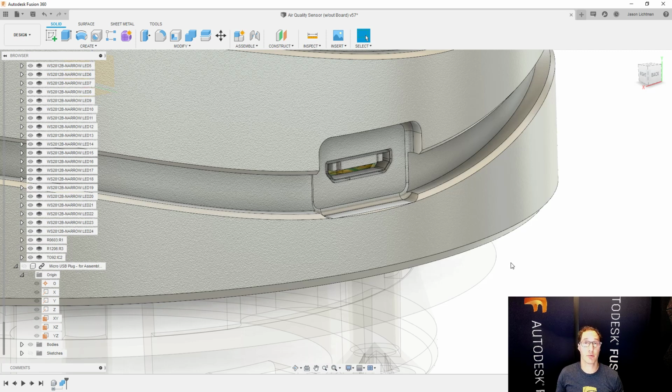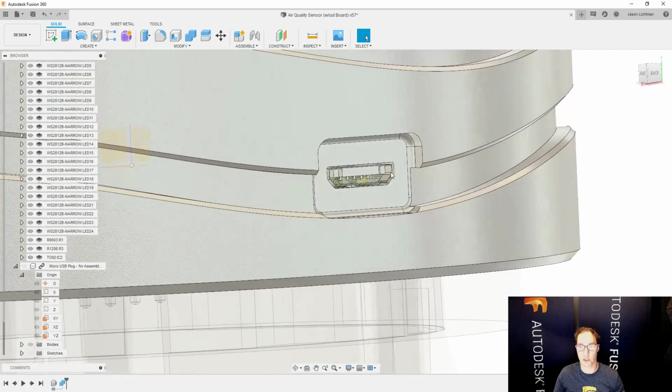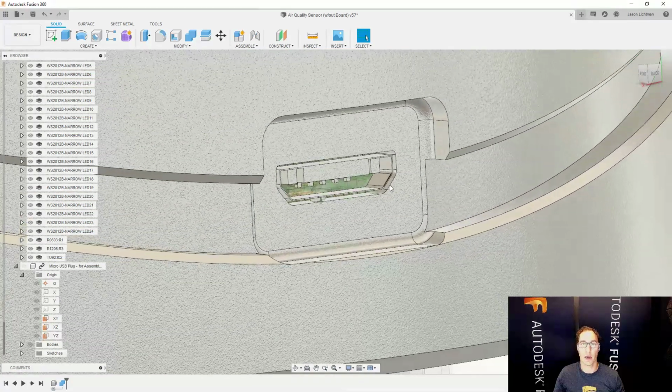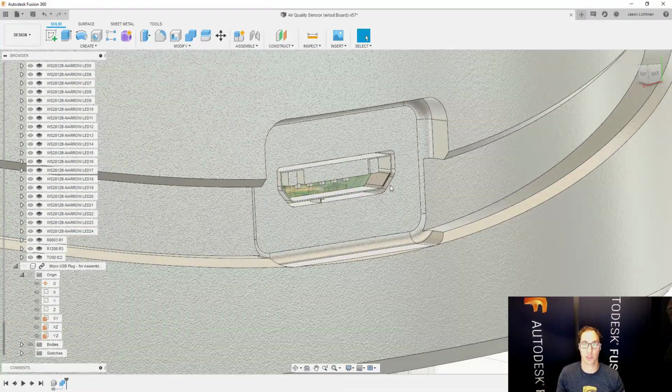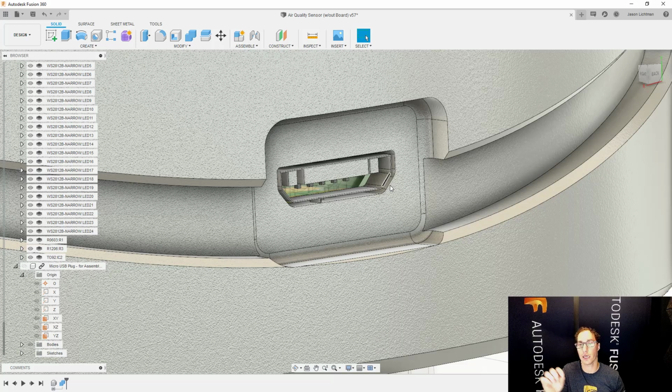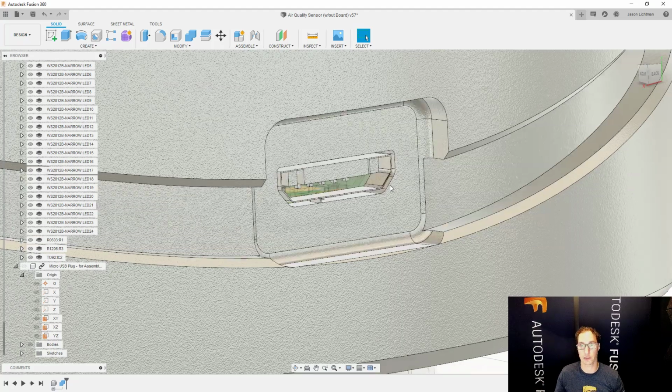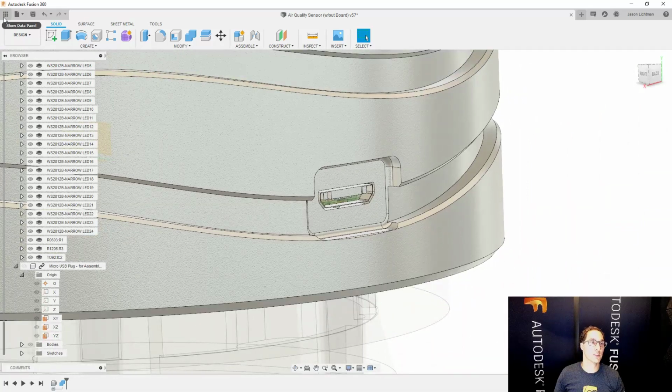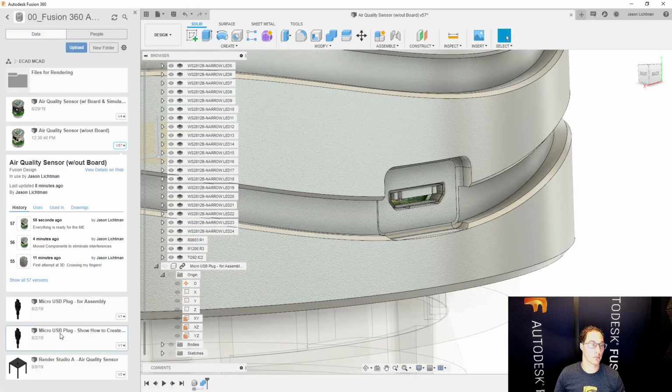You can solve that pretty easily by changing the 3D model of the male plug and adding your own offset to it. You can add an extra gap. You can reduce the detail because it's doing a little bit of funny stuff here because of the way the plug was designed, and it's creating extra bodies for pretty much no reason. So what you might want to do is go into that model and edit it however you want, parametrically or even using direct editing, to simplify the model.